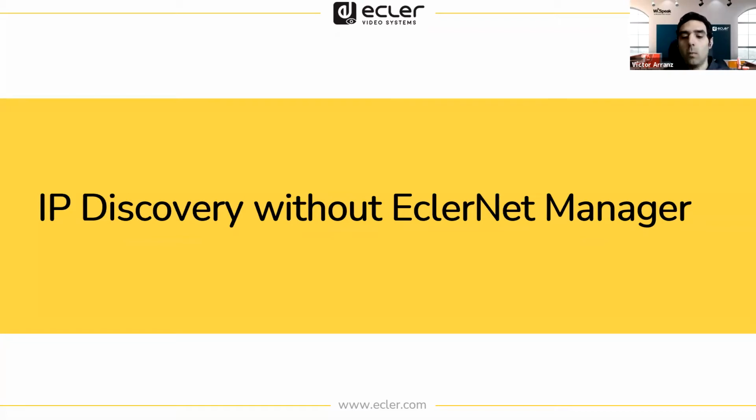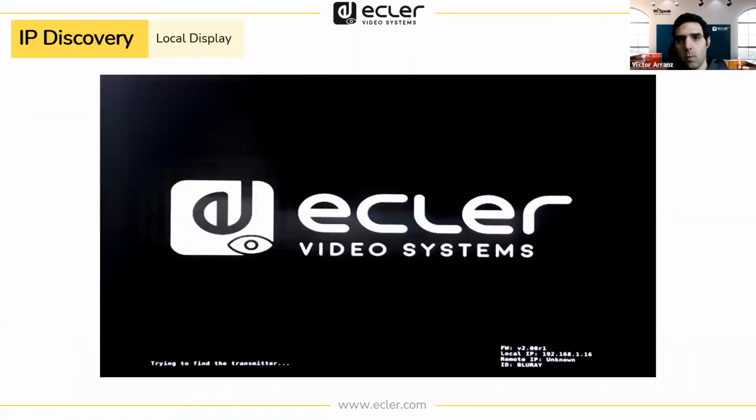But for example, maybe in that moment you don't have a PC nearby, you don't have your software. What can we do? Well, the first one, if you have a TV nearby, an HDMI display, you can grab the receiver and plug it into the TV. What you're going to see is that splash screen, right here. And if you look on the bottom right corner, all this information is going to appear. It's going to show the firmware and especially the IP of the device. This is the IP of the receiver.